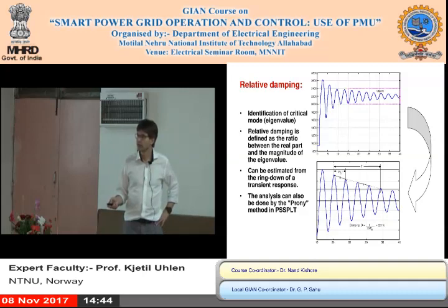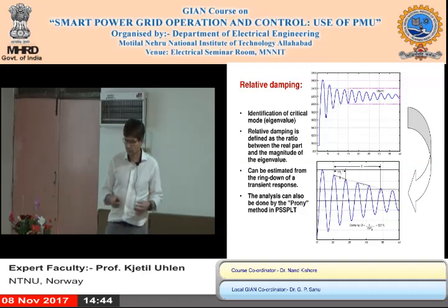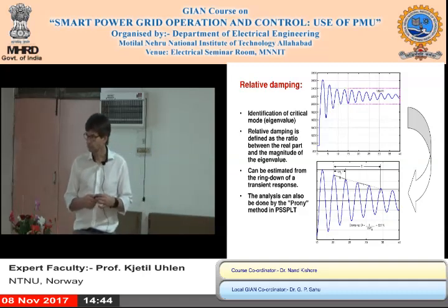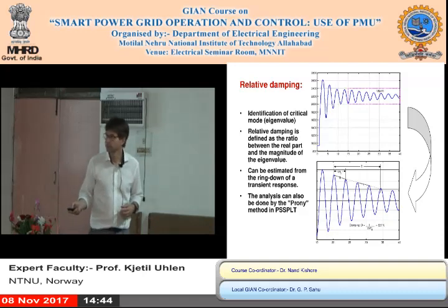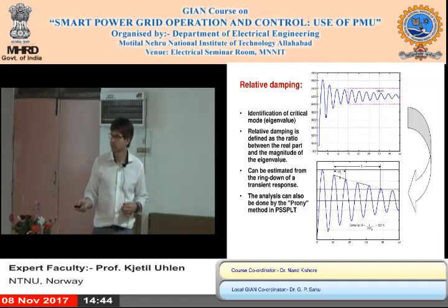So it's really about making a best fit of an exponentially damped sinusoidal signal to this and extracting the eigenfrequency and damping of that signal.